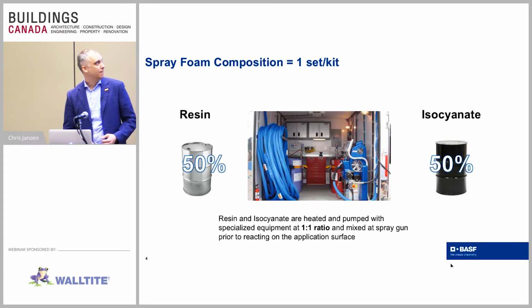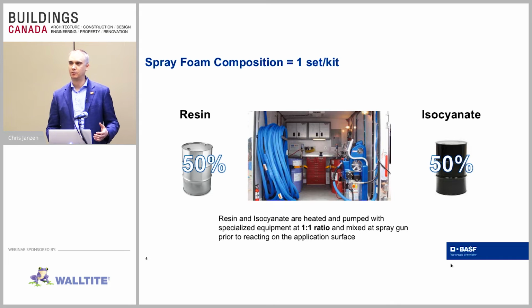One of the big things when using any kind of spray foam is that they need to see where the foam's going. We hear a lot from some general contractors about using a magic wand to put the foam into a hidden corner that nobody can see and just assume it's going to be okay. In order to get a good spray foam installation, you have to be able to see where that foam is going. You have to be able to see that substrate, and the installer needs to be able to see the foam rise. And of course, the building inspector needs to be able to look at it to make sure it's everywhere it's supposed to be. It's hitting the studs. It's properly adhered everywhere.